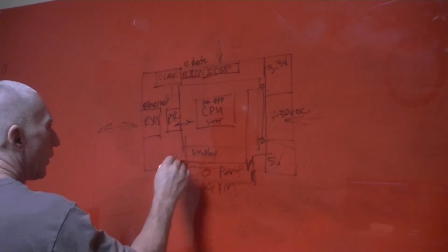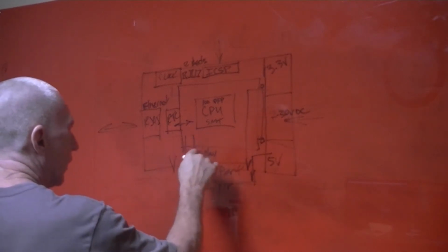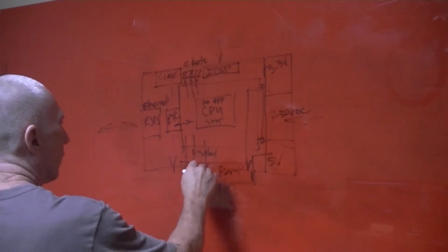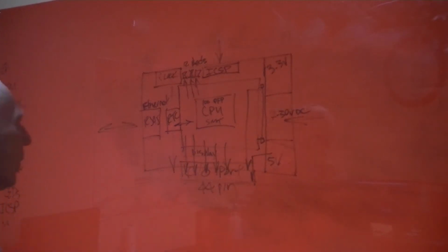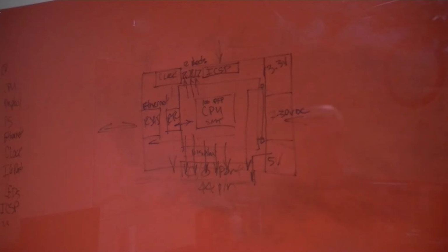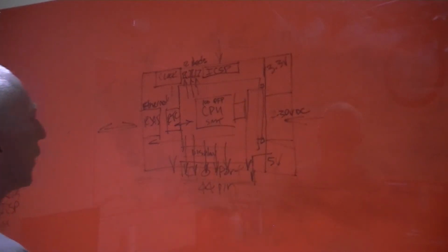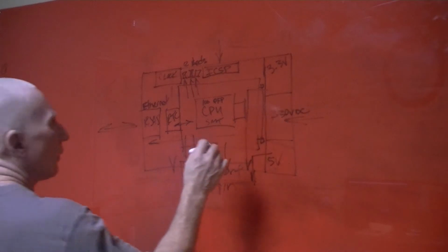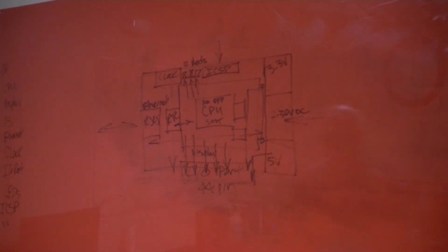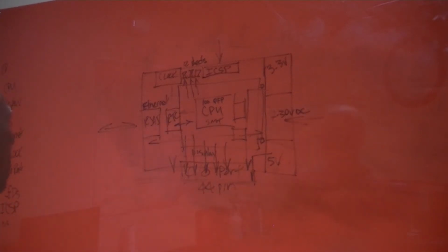We have 2 complete 8-bit ports, and then the other ports are broken up. Some are for the LEDs for the status, and some come out here. A couple pins are dedicated to the LEDs for the Ethernet jack. One port is dedicated to the display, one 8-bit port, J. A couple 4 bits, half a port is for the touch part of the screen. 3 lines are dedicated to the serial communications to the RTC.